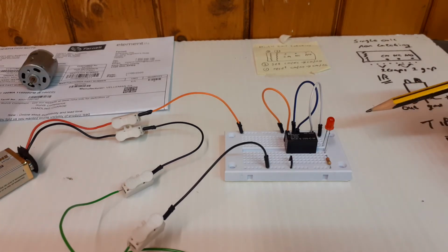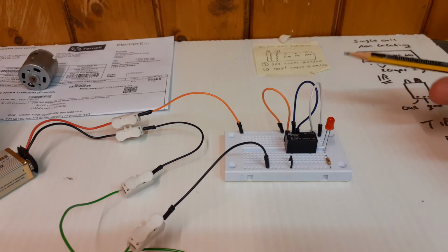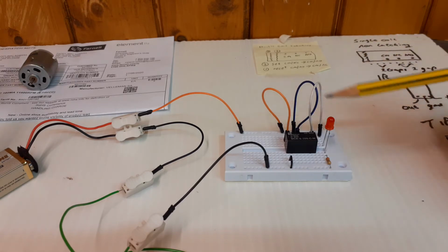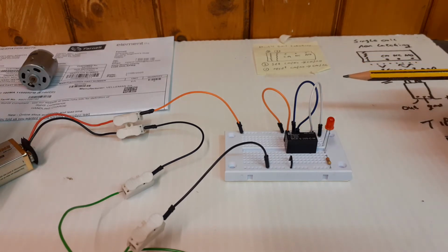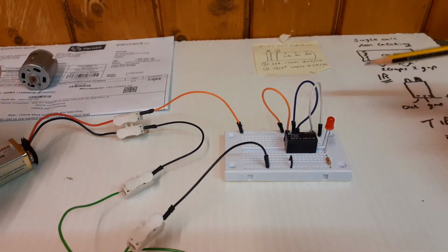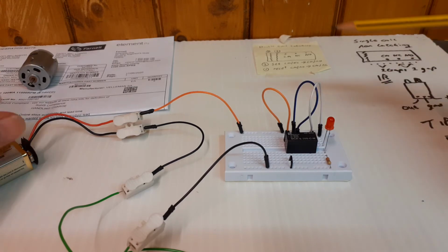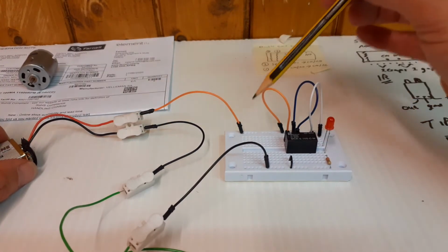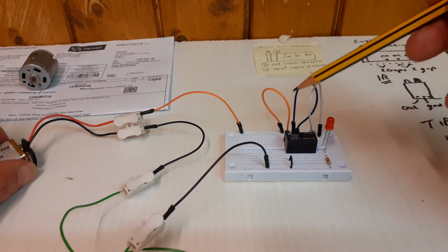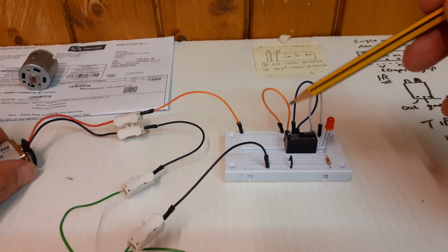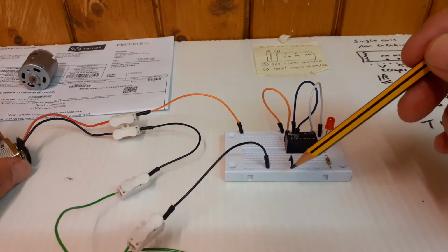Now, why do we use circuit diagrams? Because if you use a circuit diagram, it means everyone knows what you're doing. Whereas if you just showed a picture of this with all these wires everywhere, it would be hard to discern what's going on. But again, let's look at it in a bit more detail. So we have our battery here, which is our power source. That's our plus side. That's our negative side, ground. So positive goes through here and to ground.